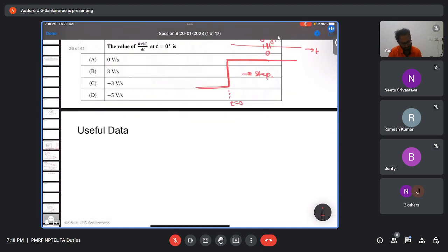So let us say for a capacitor, I have connected it to some DC voltage. Then the capacitor voltage exponentially charges, trying to rise, and at infinity, that means at steady state, it will be equal to the voltage source. Capacitor always tries to charge towards the voltage. So this is called transient state. This is called steady state.